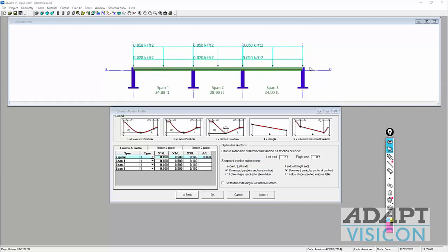That actually might mean that we over-design span 2, but since we have a majority of spans which are longer than span 2, the force necessary to meet the required design inputs or parameters is likely going to be dictated by span 1 and 3.